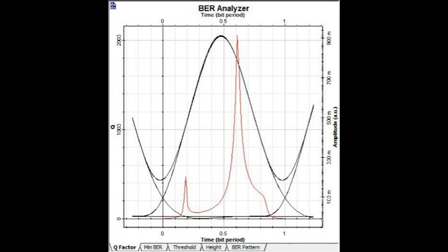The output can be seen at the BER analyzer, eye diagram and Q factor by changing range from 0 to 5 meter. When range is at 1 meter, maximum Q factor value is 4835.29, minimum BER is 0 and eye height is 1.21366, compared with range at 5 meter.